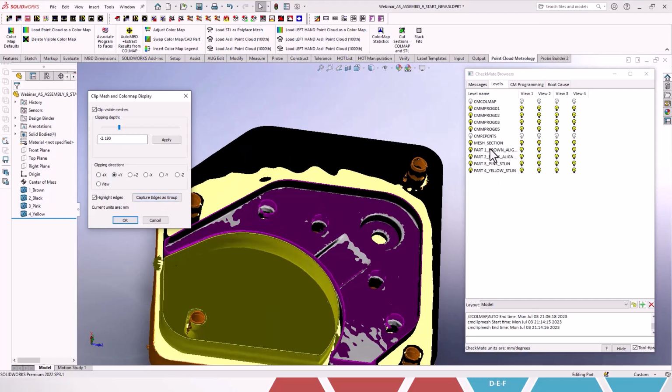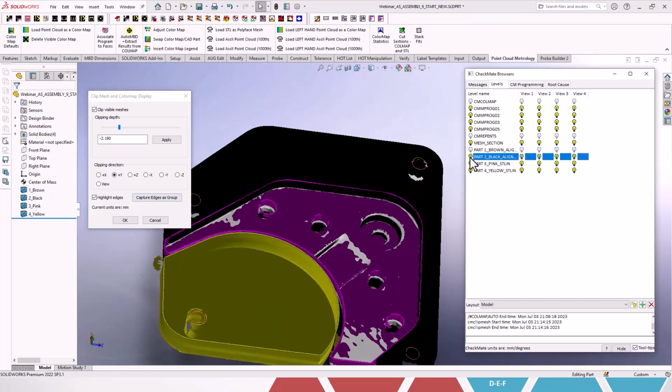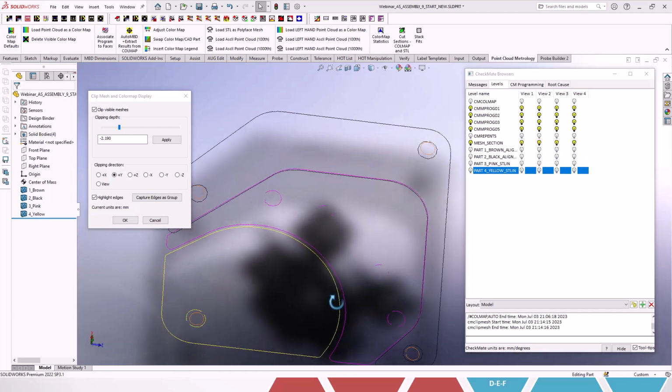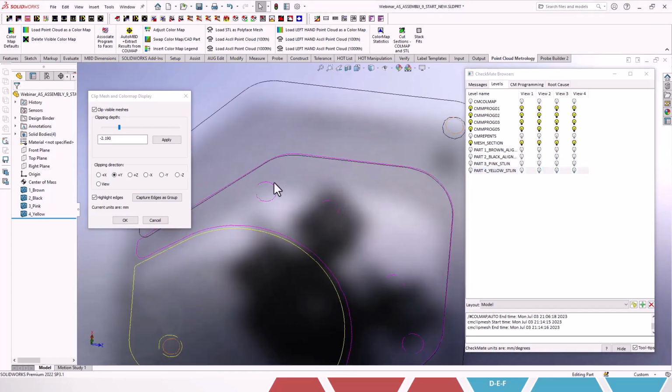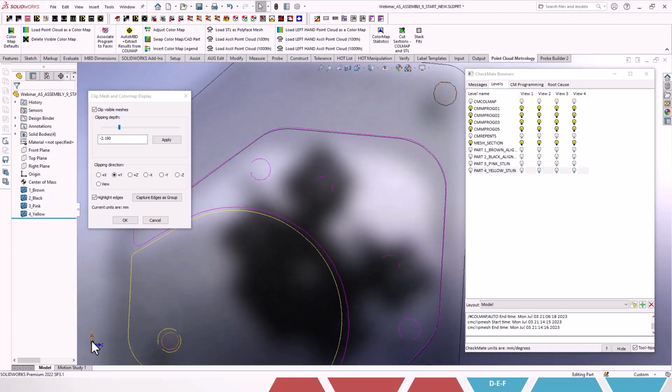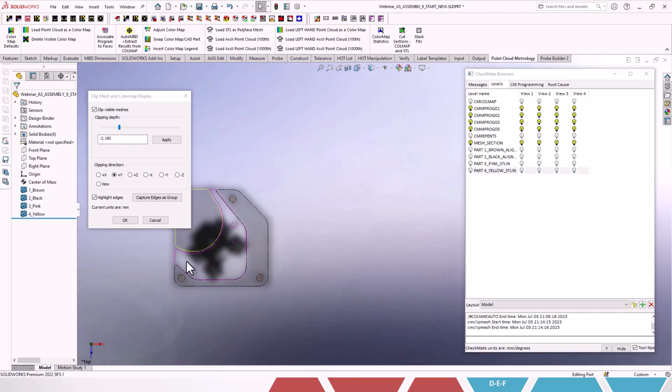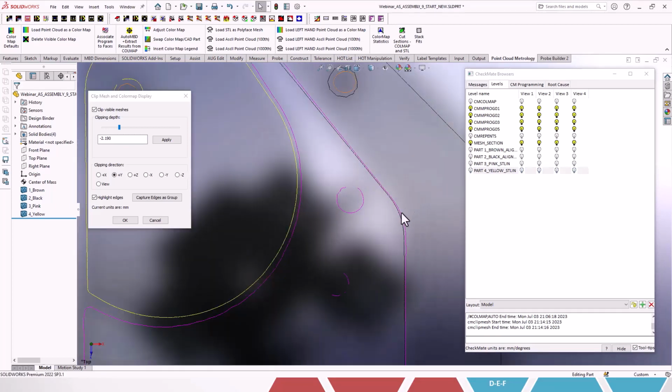You can see we got another group there, but you've got the analytical and visualization tools now to see, if I go straight down on this view, how we have an interference fit between the black and the purple part. That's really important to be able to drill down quickly and see how parts will not fit together even in their datum A, B, and C optimal conditions.